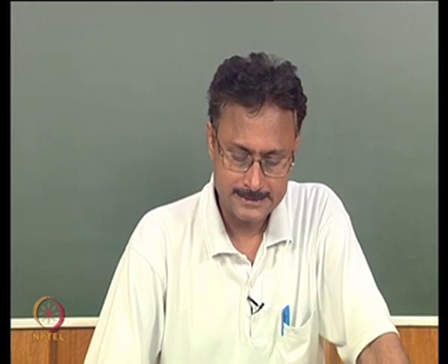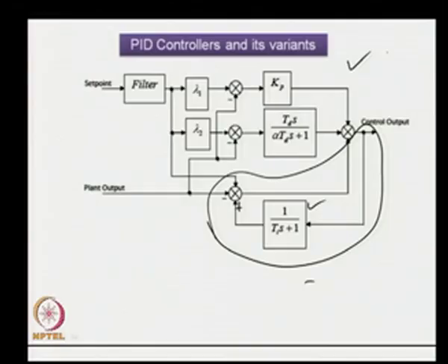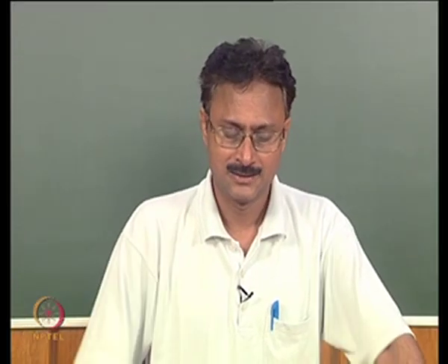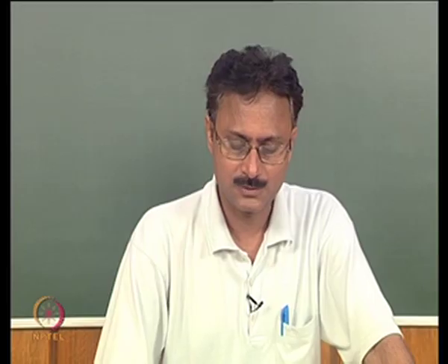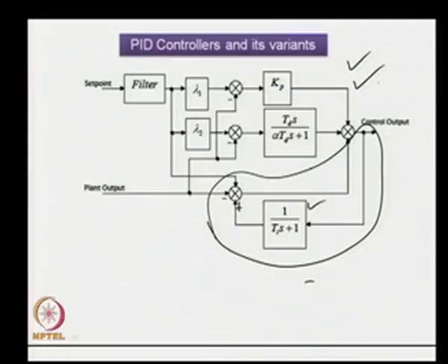So, this PID controller structure is very much used in practice in industries. Theoretically, we can have a PID controller which may not take care of the phenomenon of derivative kick or integral wind up phenomenon, but practically one needs to employ this sort of controller to overcome those limitations.